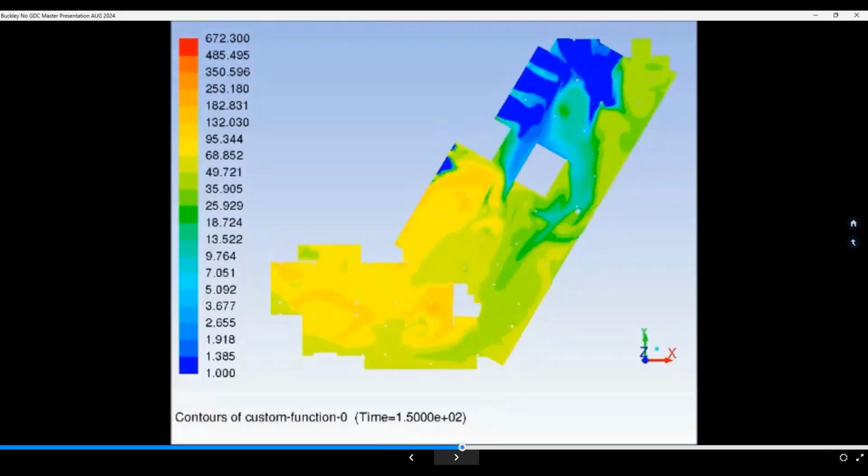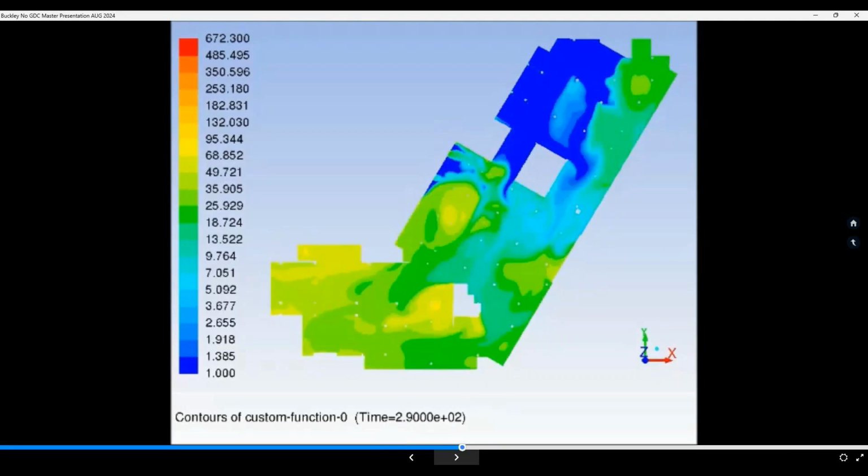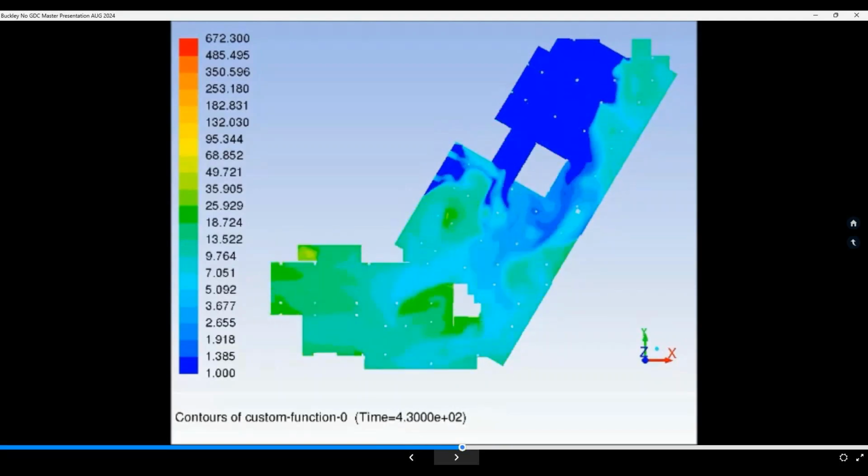Now, with jet fans in operation, a couple of different things you see here. One, you have a much better uniform cleansing of the garage. You have a much better reduction of carbon monoxide. And even down here at the bottom left, because we use the jet fans and the supplier of the jet fans to control the flow distribution throughout the garage, we can actually capture this air at the bottom left corner where we were having all that short cycling and eliminate it. So the garage space is actually getting full benefit of the ventilation rate that's been introduced, which is required by code.